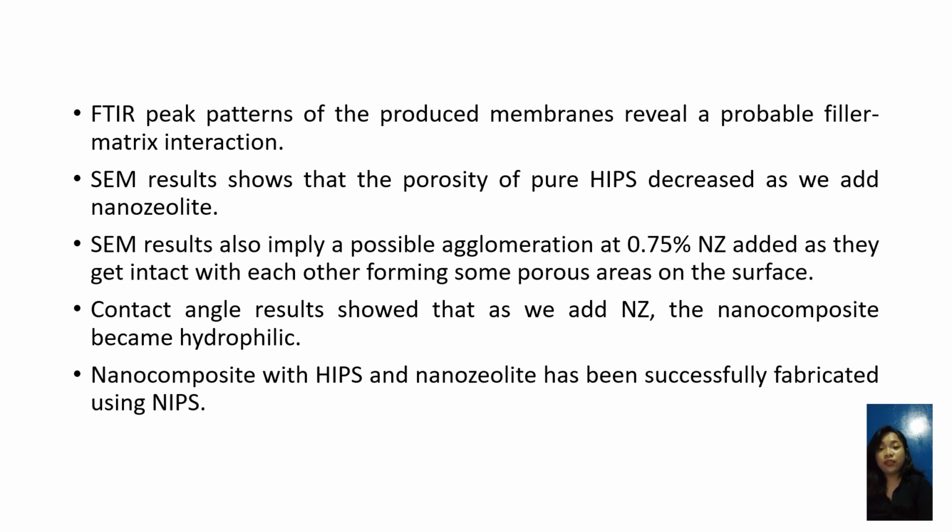Contact angle shows that as we add nanozeolite, the contact angle decreases, making the nanocomposite hydrophilic. Because of its porous nature and the presence of polar species within the zeolite structure, nanozeolite has a significant potential for water suction and absorption.